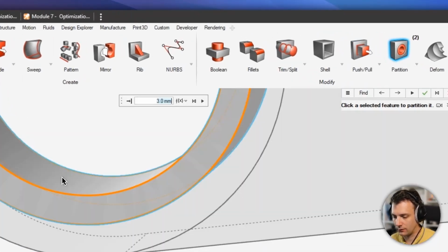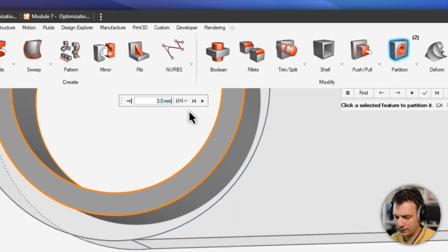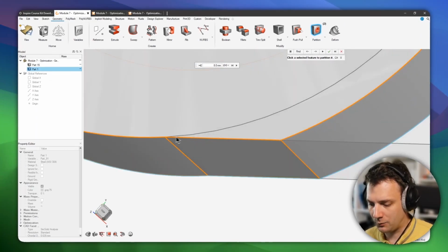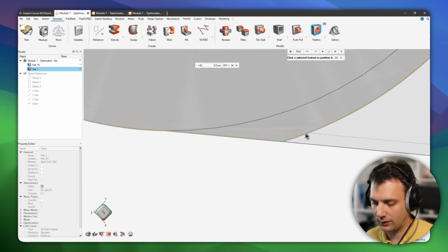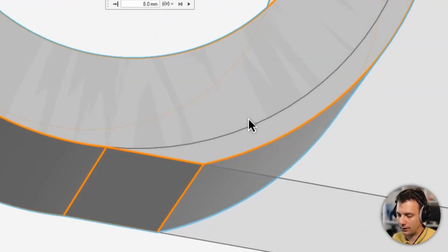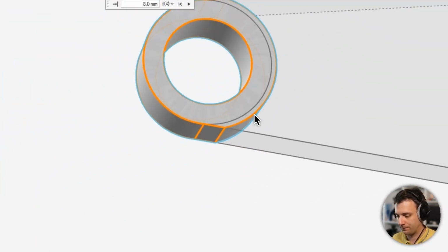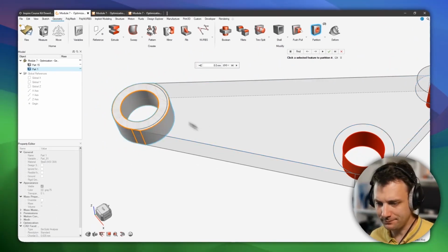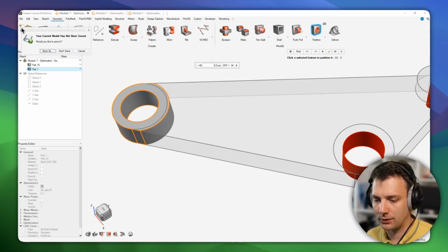You click on this, for example, and then as a size, let's just say 8. And you see, this would be the edge you would have to deal with using the tangential line, and this would be the edge. See how it loses its sharpness, its steepness, or however you would call that. So it loses the edge, and that means it's easier for the solver to handle. So those would be my two comments on geometric modifications. And then let's quickly look at the model, how it's set up.